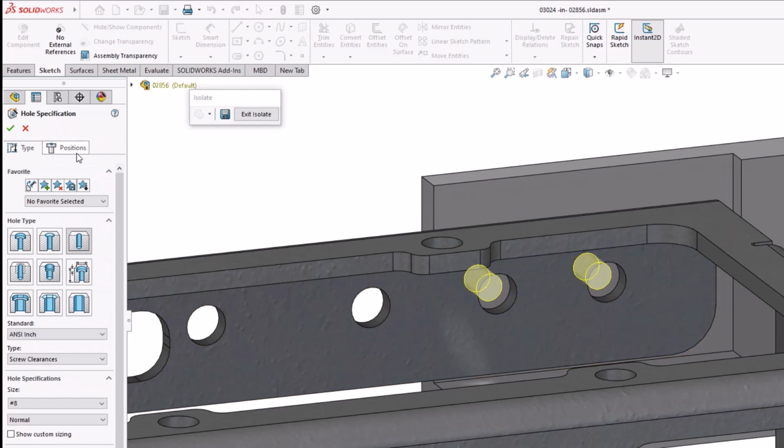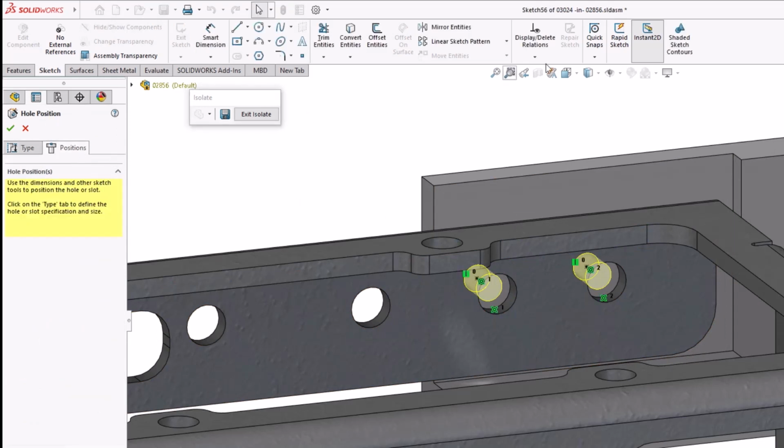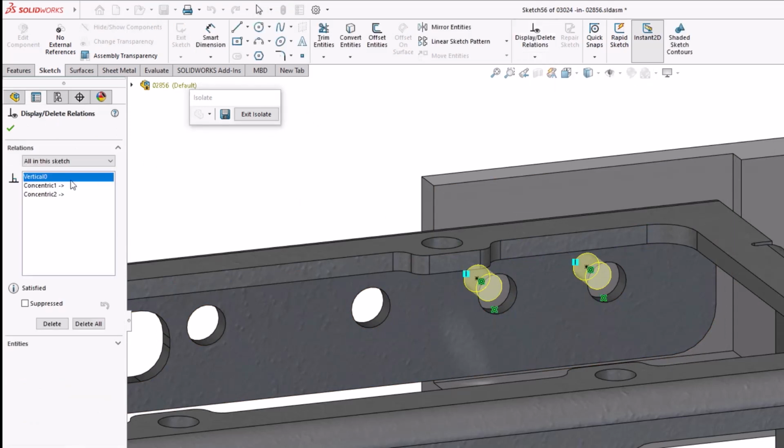This is a common top-down design practice to ensure that the holes always remain aligned to one another. However, investigating the second component's feature, also a hole wizard, it appears that the center points within this sketch are likewise referencing the edges of the previously interrogated holes.